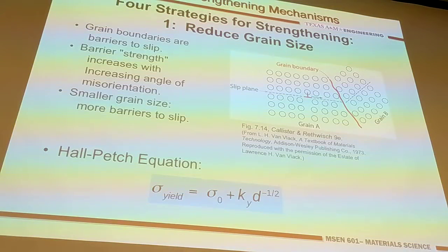What's the meaning of yield stress, by the way? What's the definition of yield strength? The end of the elastic region. Reached when you note there's a noticeable amount of plastic deformation. Yeah, a noticeable amount of plastic deformation in metal, corresponding to that generated by dislocation.